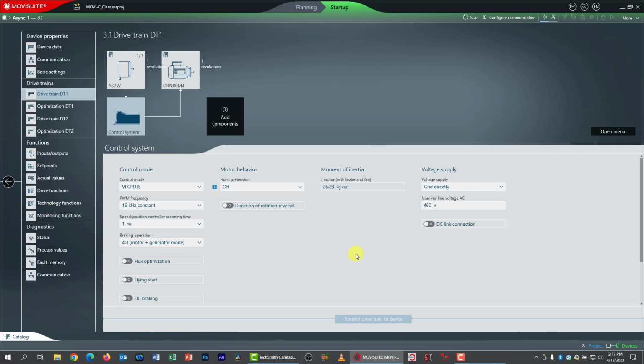Now what we're going to do is configure the access so we can use the jog mode function control block, FCB, to operate the drive. We're going to jog the drive using some switches on our control box, in other words, digital control of jogging. We need to assign 4 of our digital inputs to control that FCB, the one associated with jogging.